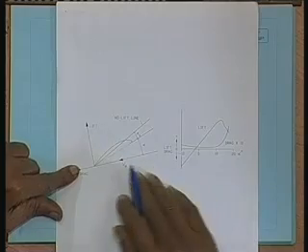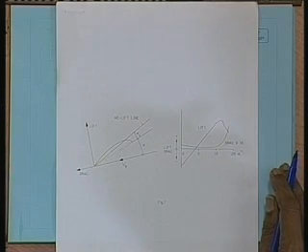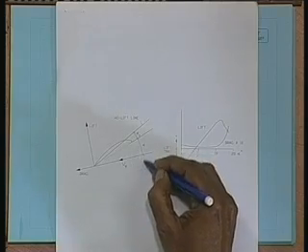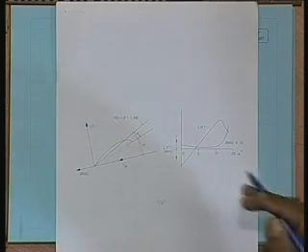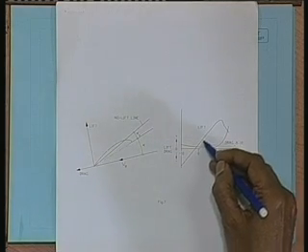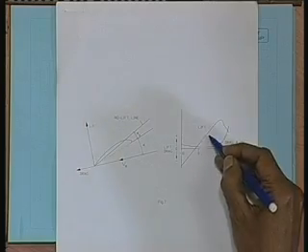Yeah. So let us look at this diagram a little bit. We also know from aerofoil theory that if you go on increasing this angle alpha, called the angle of attack, if I go on increasing this angle of attack, lift increases more or less linearly like this, as is shown here.